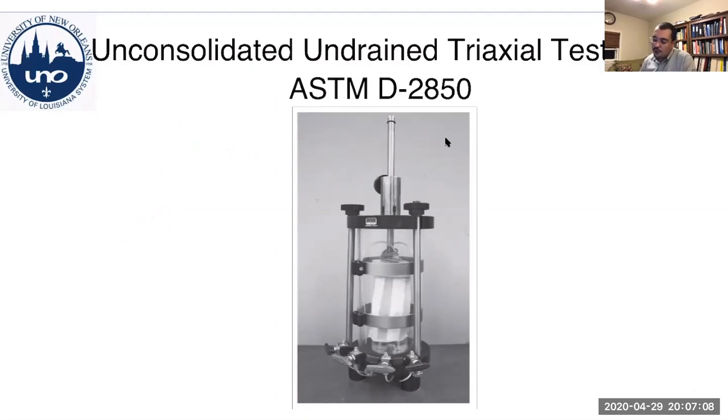Also, Casagrande developed this test, and what he was trying to do is have a little more control over the drainage conditions and over the pore water pressure measurements that you can get throughout the test. Although we know that you can run a direct shear test slowly enough to have drained conditions, here there are more precise measurements during the consolidation phase and during the shearing phase of a triaxial test. So you have control over the drainage conditions and pore water pressure measurements inside the sample.